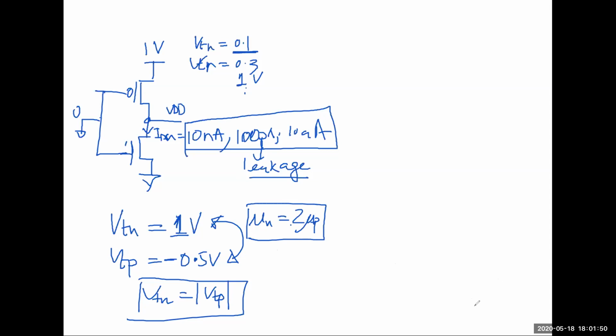In one interview, the characteristics curve which we are talking about, this is the input and output characteristics curve from the voltage point of view, that is Vin versus Vout. In one of the interviews, they asked for a current curve with respect to the input voltages. So that means output current curve with respect to the input voltages.